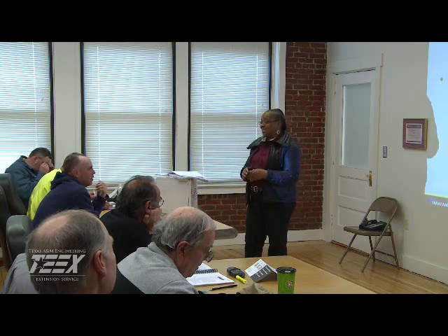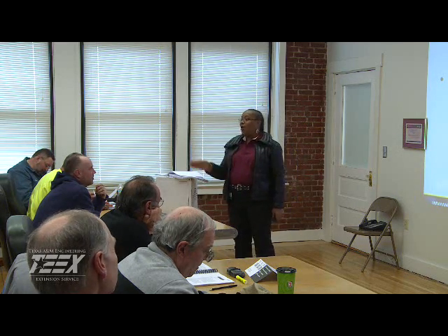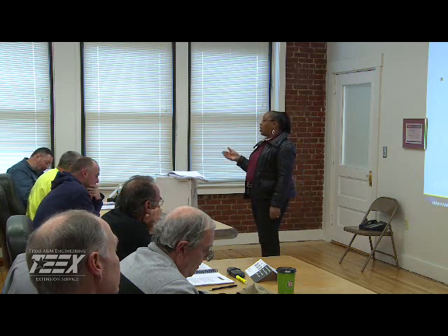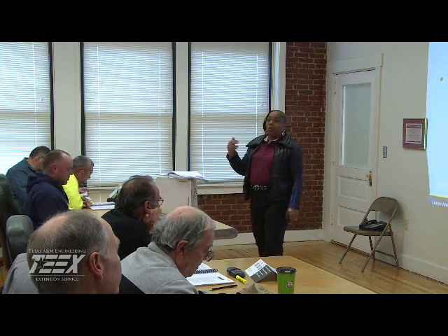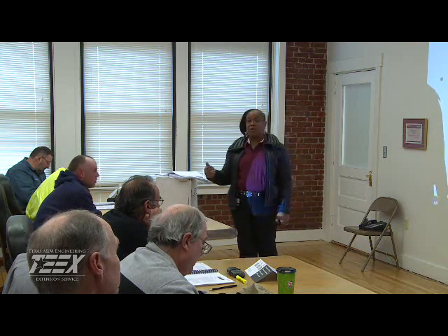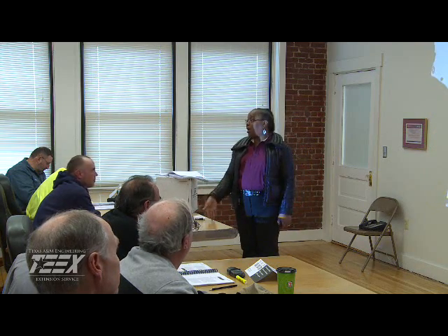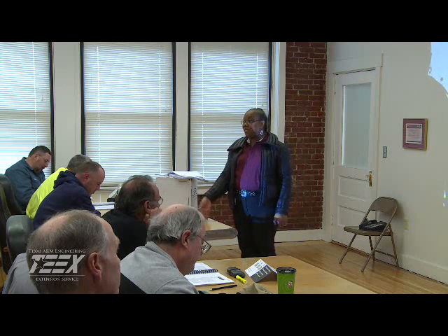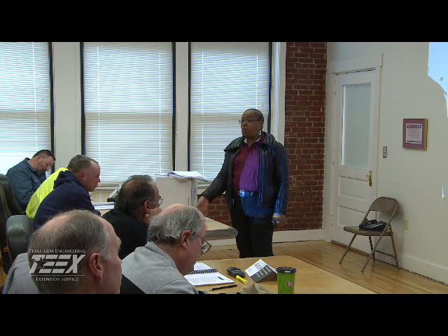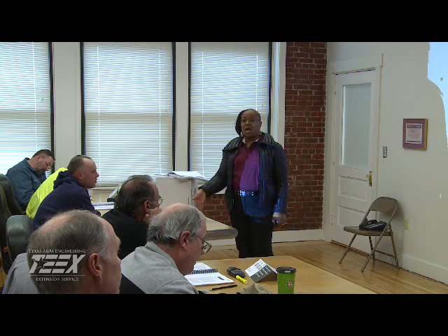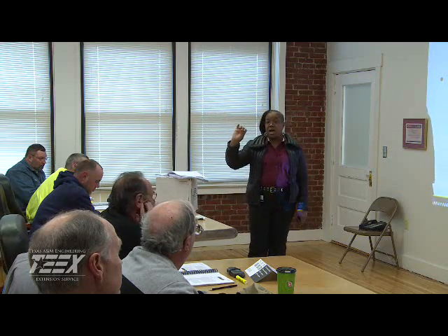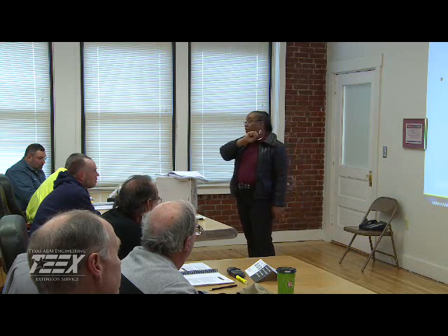we're following the letter of the law. And when we retest, one of the stipulations is we must go back to that same site as one of our retest samples. If I have more than one routine sample, for every positive, I'm collecting 3 repeats. One from the original site, one within 5 connections upstream, one within 5 connections downstream to pinpoint where the error is.